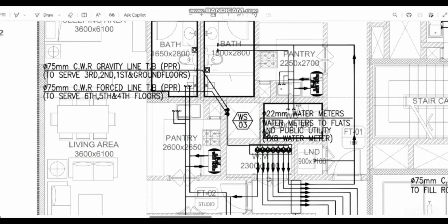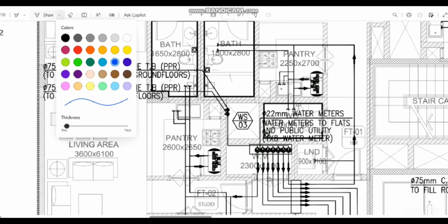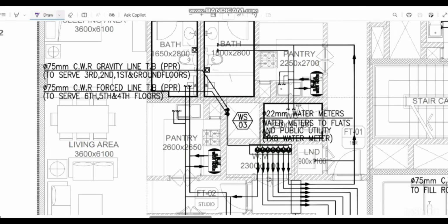When it comes to water hammer arrestors, we normally make a common mistake that I have explained here. For example, in our case you can see the supply line coming from here, supplying this water heater, going to the kitchen sink, to the bathtub, as well as to the wash basin area and water closet. Normally, before the wash basin we provide one water hammer arrestor, so it will absorb the shock before it goes to all the other fixtures.